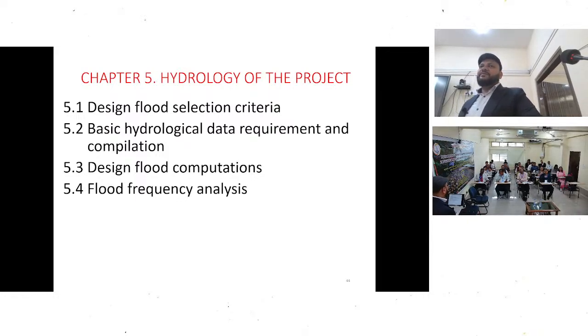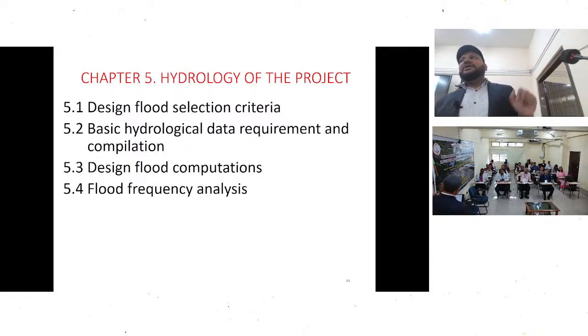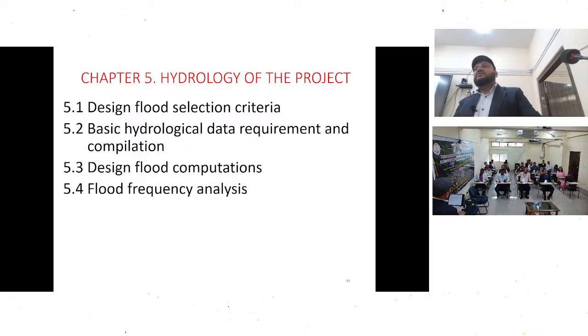What I have to say is, if there is a very important installation, then we will construct for a 100 years flood frequency. Suppose something important like the parliament building has been made, then it is made for 100 years, maybe 200 years. Ram Mandir has been made, it is also made for a very long period. Suppose a small thing has to be made, then we can make it for 5 years only. So we have to do flood frequency analysis for the design flood frequency. This should be discussed in the hydrology of the project.